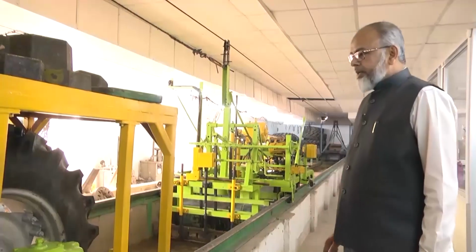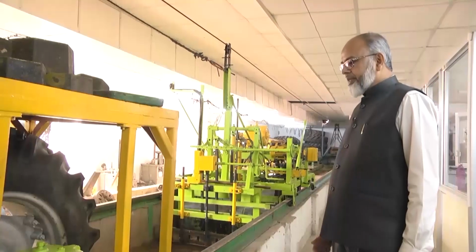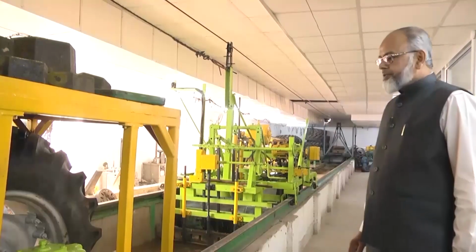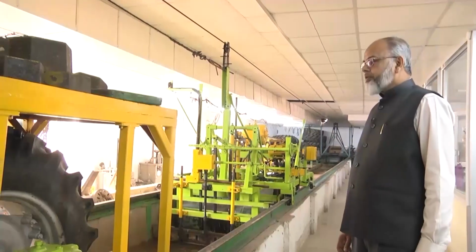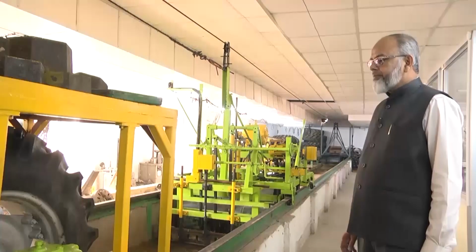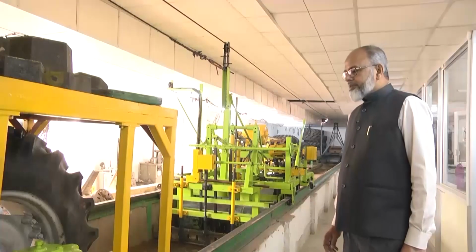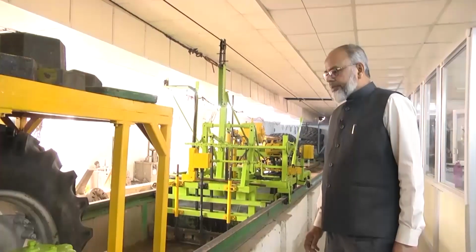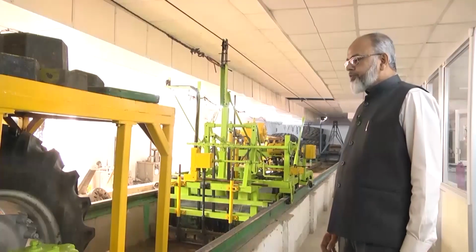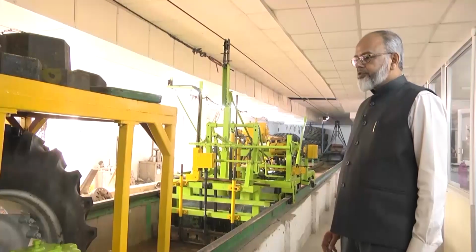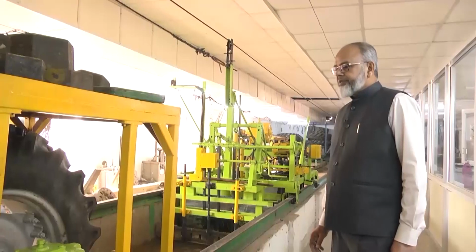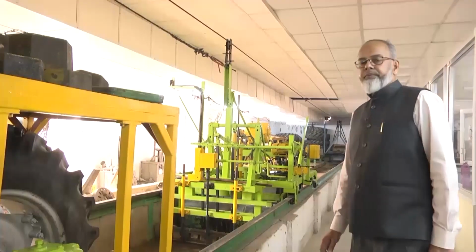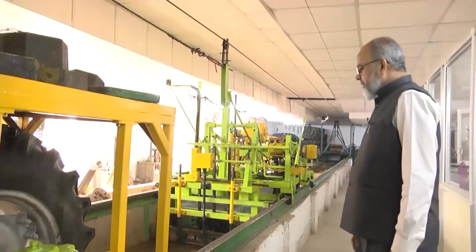We can change the tire, we can change the load, we can change the pressure, we can change the soil condition. And the parameter which we are going to measure is the cone index of the soil, which will indirectly give you the strength of the soil. Then we will find out the moisture content, and how much pull you have applied, then the corresponding slip has to be measured, then tractive efficiency. So these are the parameters which are required to evaluate the tractive performance of a tire. So to start with, I will first